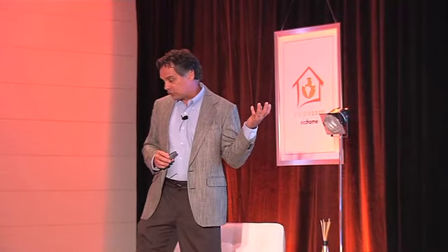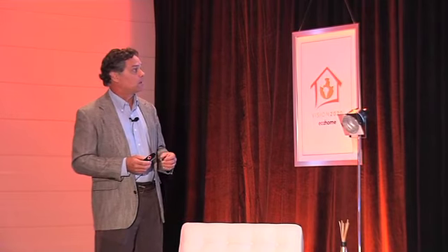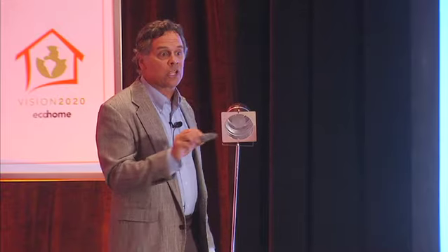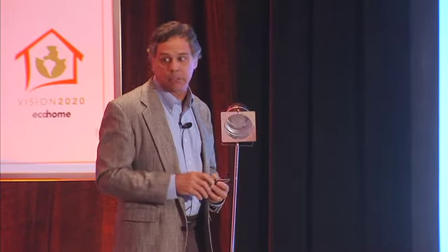Now, one particular tool that we've found really, truly amazing is WUFI, a software modeling program that takes a look at the water and energy management for an entire building assembly. Okay? Remember those 10 layers and those 4 states of matter? WUFI is a program that can analyze every single individual layer of the assembly, as well as the assembly as a whole, in terms of all the heat and all the moisture flows in the assembly. Looks like a wicked complicated tool, but we need that to understand the physics if we're going to build these really complex assemblies.